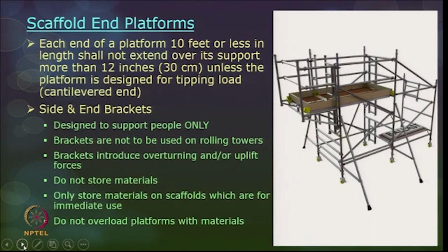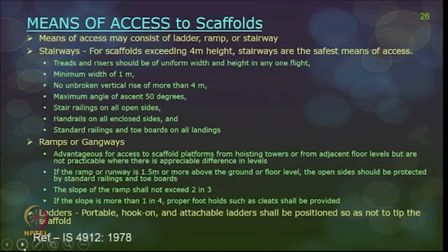Do not store materials, and only store materials on scaffolds which are for immediate use. If it is for long term use, if you need something only after 1 day or 2 days, then do not load those materials onto the scaffold. Also, do not overload the platform with too much material, because it can be a trip hazard when workers are passing by the scaffold.